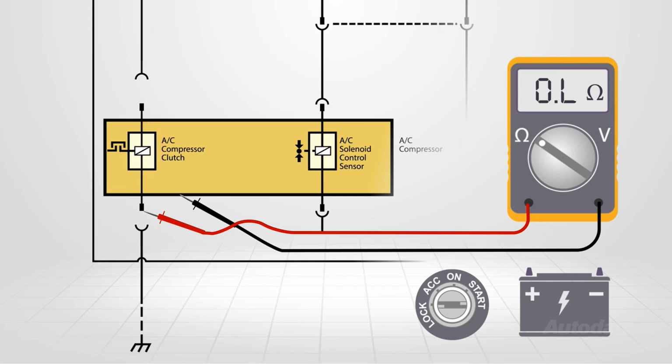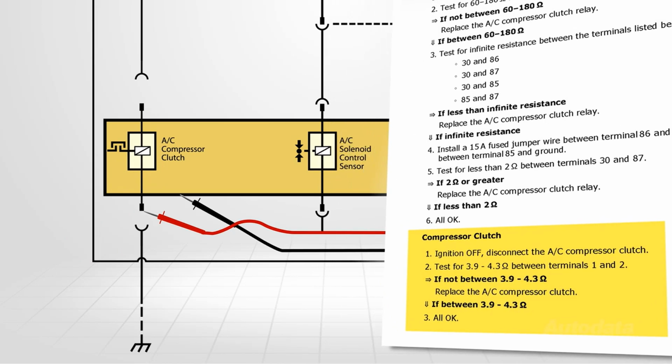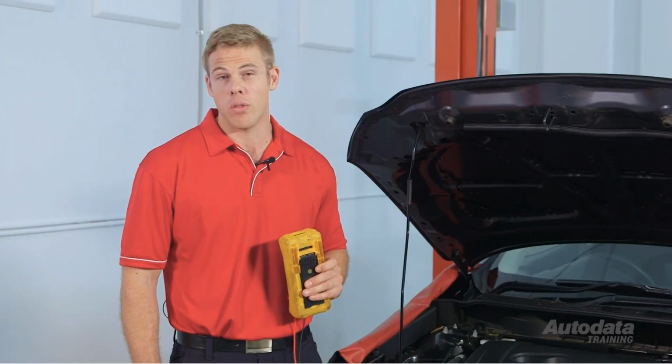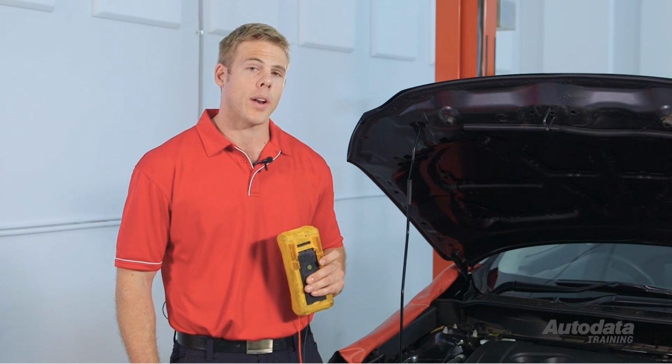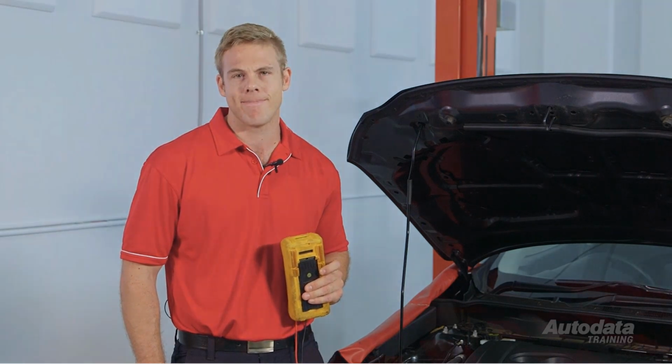It's a good idea to check with the manufacturer's specification for the clutch coil resistance, as this will further eliminate an excess resistance fault. If initial testing showed no voltage, or less than required across the harness connector, further diagnosis of the control circuit is needed.